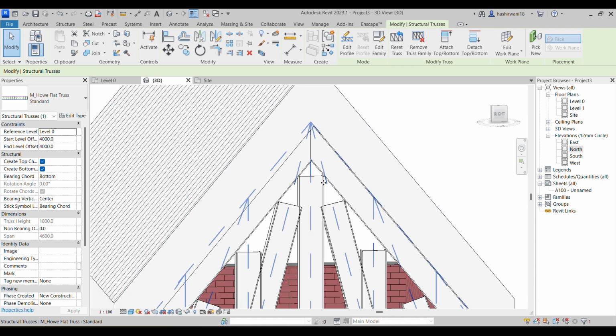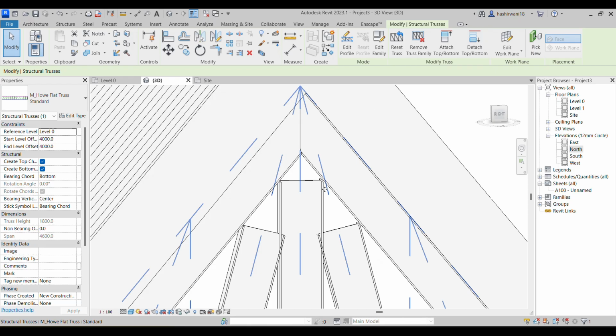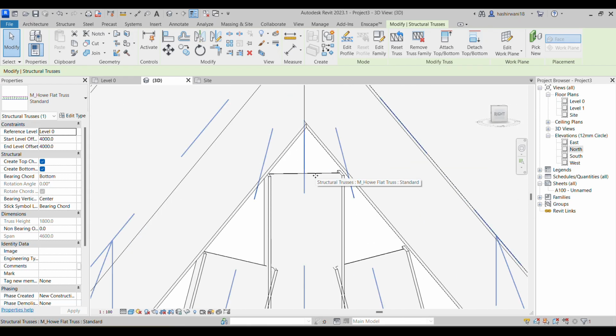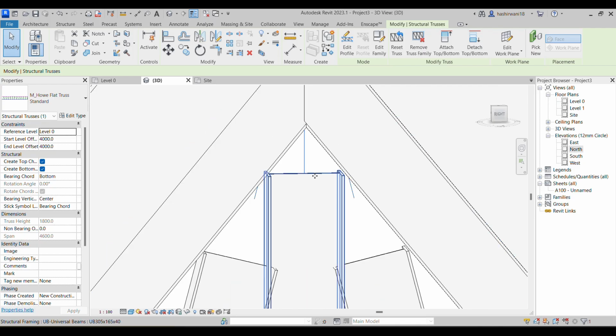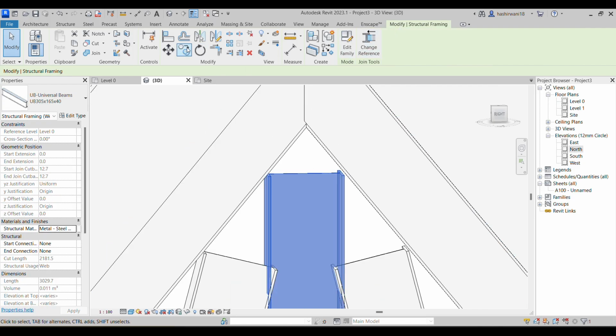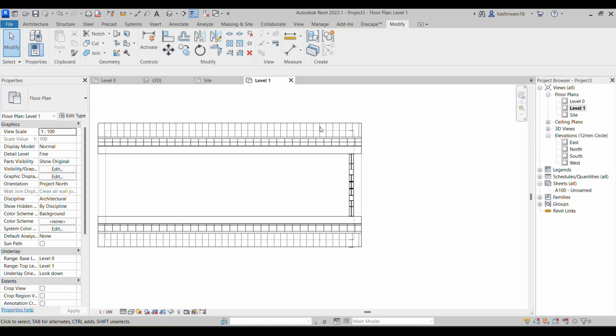Now what I want is, sometimes, can you see, these have been cut off. So what I want to change, this. I can simply go to tab option here. I'll select this particular element, and then in our modify settings we have an option called cope. We can use those cope options to move them up and down.